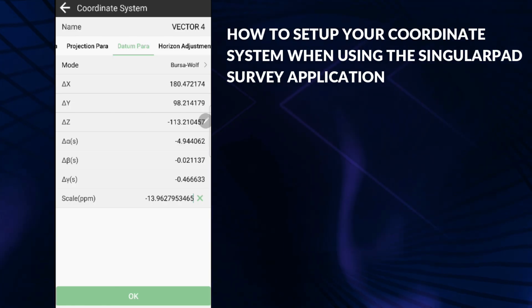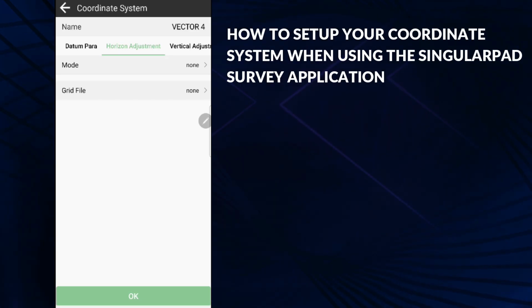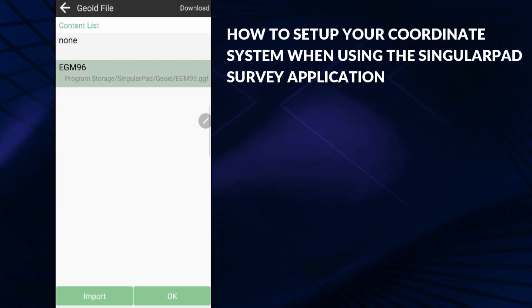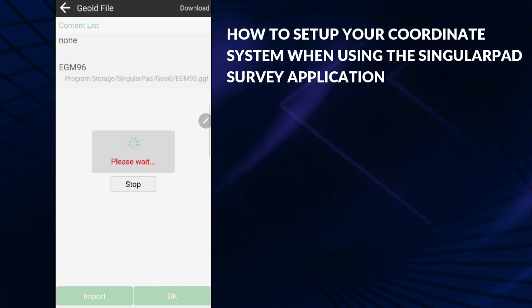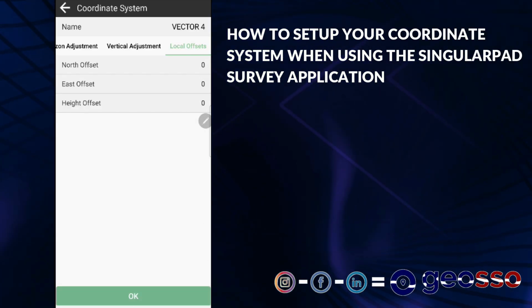We'll go to the next page, which is the horizontal adjustment. On the horizontal adjustment page, we'll leave it at none. Both the grid and the mode are going to be like that. So on vertical, if you have a geoid model file, you can select it. But I'm not going to use this. I'm going to skip. Now last is a local offset. I don't have any local offset, so I'm done.